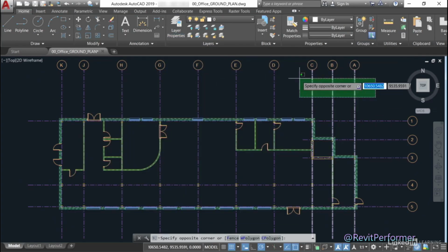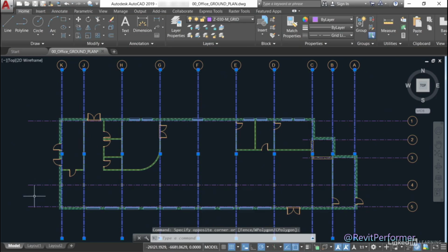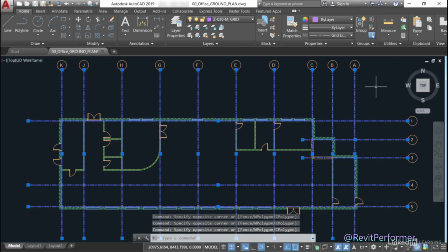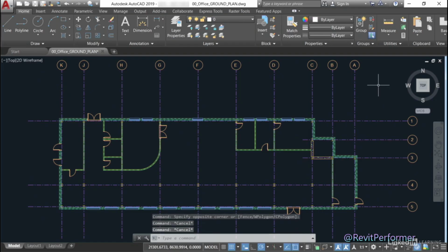I'm now going to select all of my grid lines. Make sure you get all of them, like so, and there's a couple of short ones there, remember that as well. And what I'm going to do now is in the properties panel, make sure that they are using by layer. Escape to deselect, and you can see they're using that grid line type now, but by layer rather than as individual objects in your AutoCAD drawing. Now that's all the stuff that you need to set up in your AutoCAD drawing. It's important that you do that, and then all of this information can be retained when we start to generate templates to create our CAD drawings from.